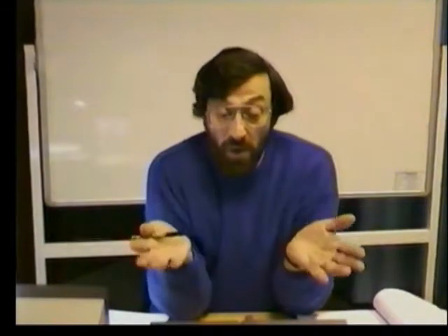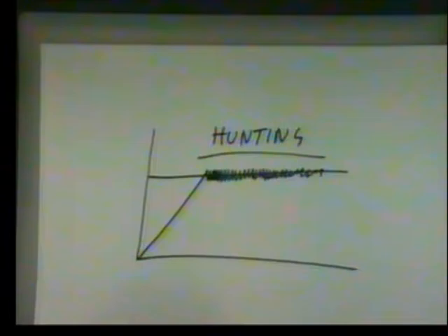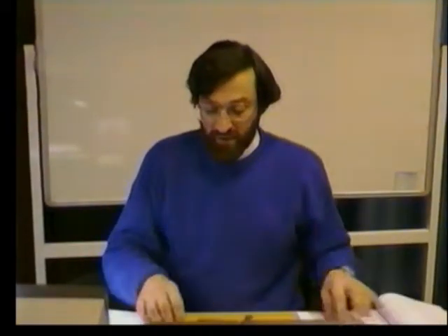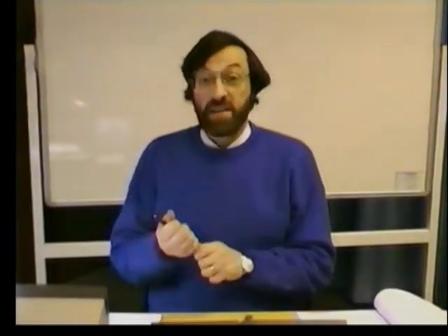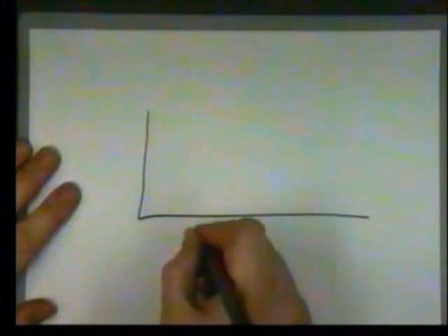Now, in general, all on-off systems exhibit hunting. But what you want to happen is for the frequency of hunting to be nice and slow and smooth. What you don't want is the high frequency oscillation that will cause the system to destroy itself. So let's think of some techniques to control this process. The most widely used one, and the one that is most effective, is a process known as hysteresis. What we do, let's draw our graph again in time.